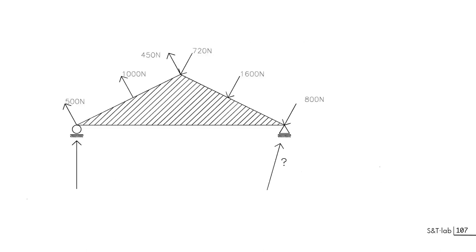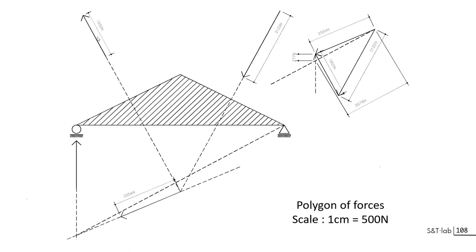We'll just replace the system by 2 forces. So this is the resultant of the force applied on that side, and this will be the resultant of the force applied on the other side. From this, you are able to start building the equilibrium of the 3 forces: 1 force, 2 forces, and the last one will be corresponding to the sum of reaction forces. So I take a parallel to this line here and a parallel to this line here, having a resultant on this line.